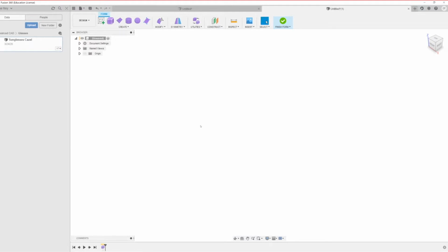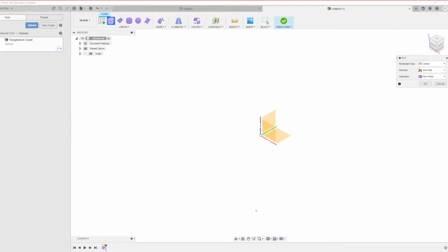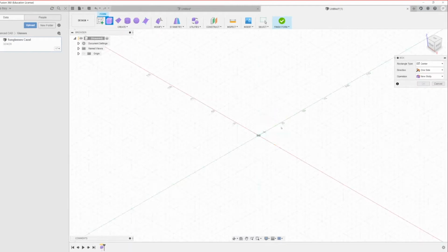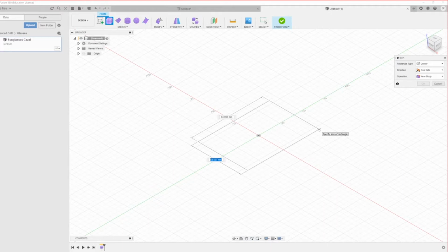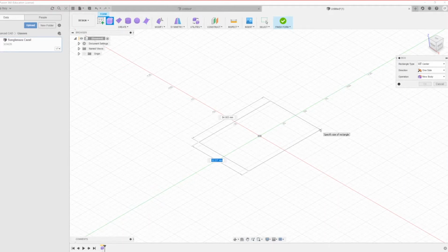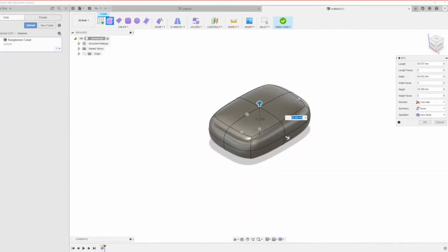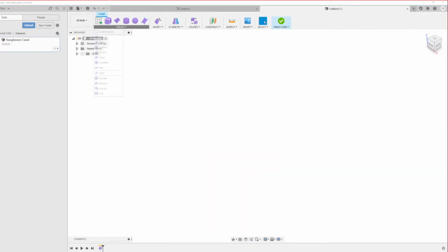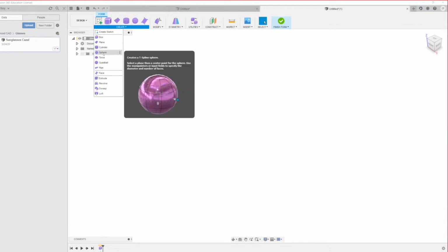The way this freeform works, first you simply enter it by creating a form. So in Solid, you go into Solids, into Form. When you create a new form, it does create a new feature in the timeline, but it is like another program in Fusion essentially, because it works quite differently. So we have all these options that you can start with and all these different features which you can actually do and modify as you go along.